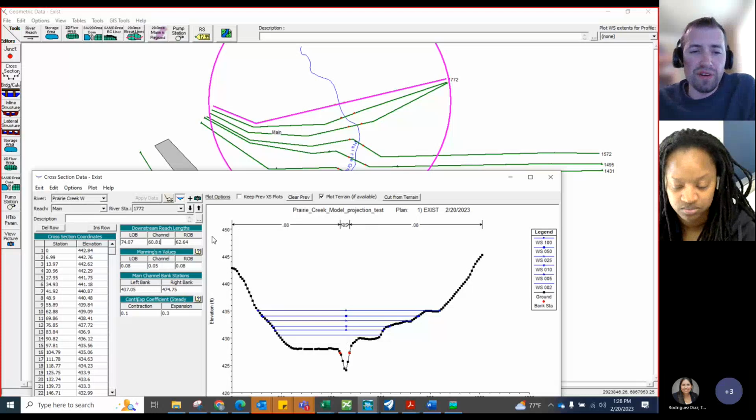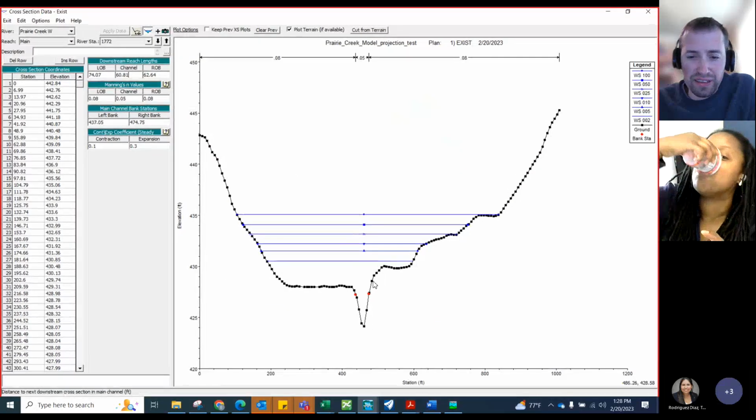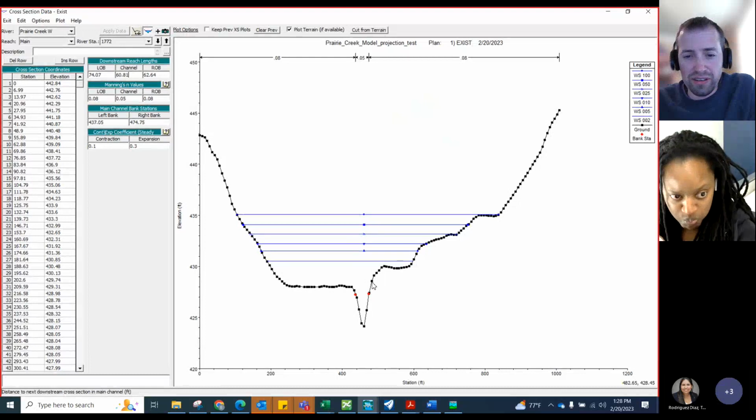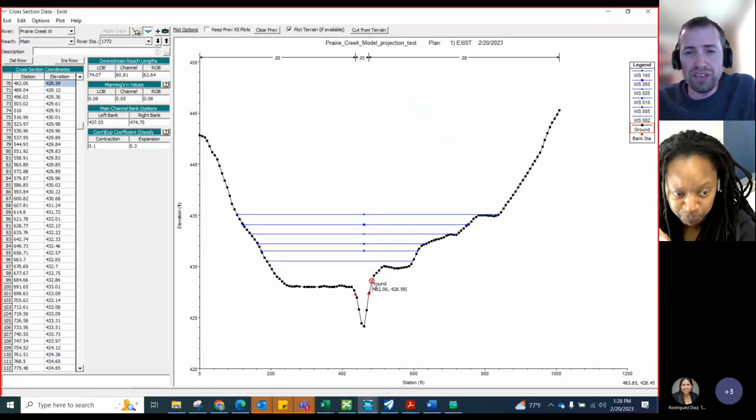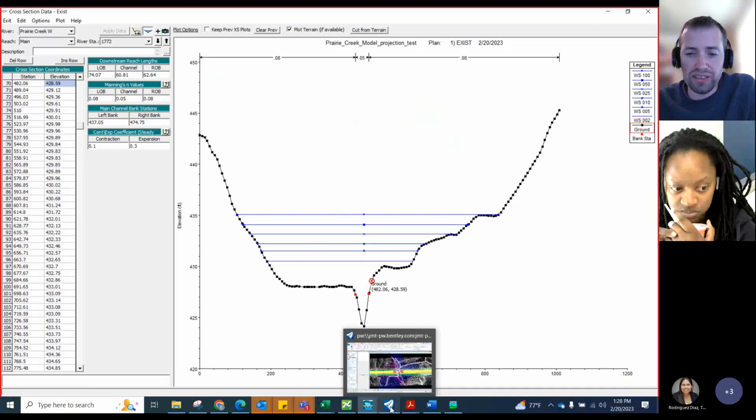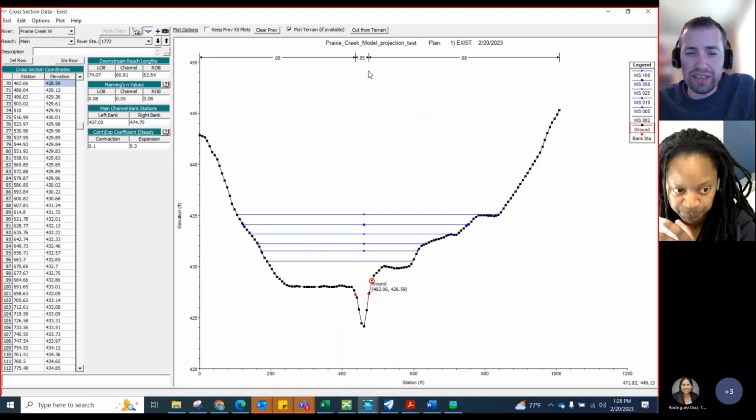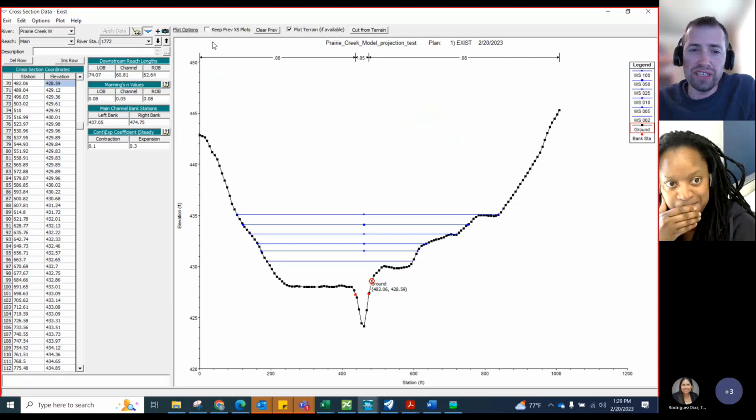But say you're looking at this and you think this is really the channel, I want to change that. You don't need to go back and redo anything on your drawing, because all that's affecting is your Manning's n value. The reach lengths are generated from the other lines, so you can still make tweaks like that.